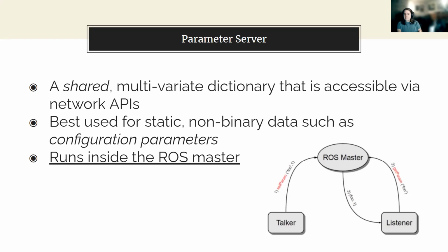And that's a simple example, but I hope you can see how that might expand, right? If you want to change certain parameters about your robot, or maybe you have some path planner that you want to subtly tweak certain things about, you can do all that from within the parameter server instead of having to go into your code and playing with each of these values every time. It allows you to easily centralize all of the configuration settings you have for your entire project, which is really nice.